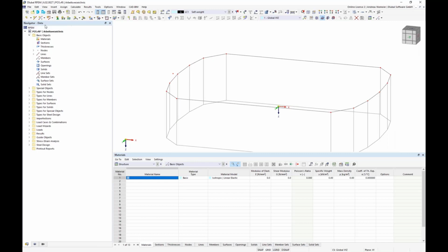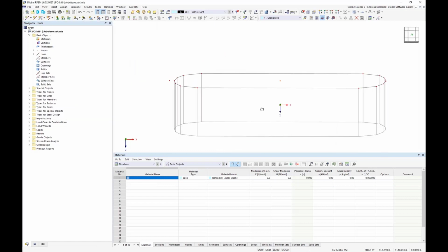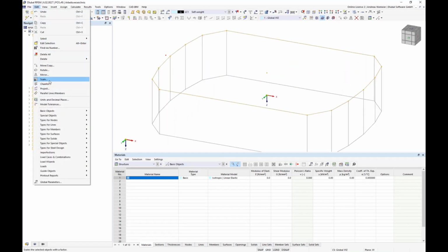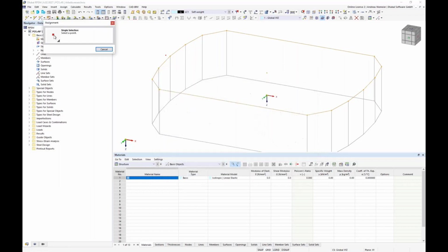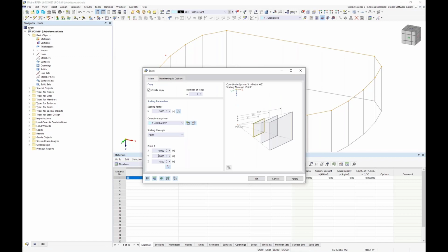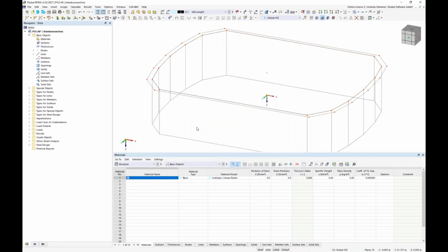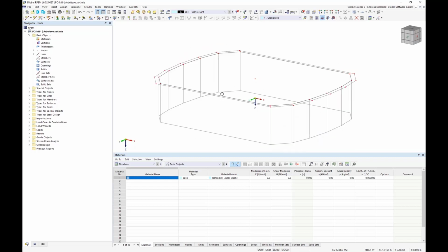covered by the roof. And for the scaling, I create here a center of scale. Therefore, I pick here such a center, and now we can take this basic geometry, select it with a window, and start this command scale. Define that we want to copy it, and the base point of this operation is this point in the middle that we just created, and the scaling factor we pick here directly by defining the original length and the target length. And with confirmation, we now get our final expected edge of membranes on the eave,